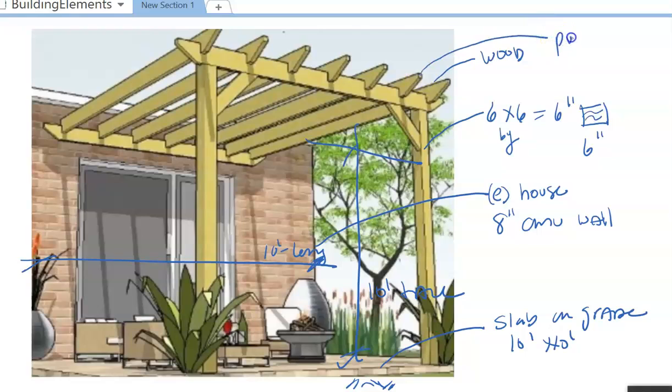They're also beams, but there's just more of them, and they're at 2 feet on center. So this distance here is 2 feet. And those purlins, I think I said they're 2 inches. I think I said 2 by 6. So they're 2 inches wide